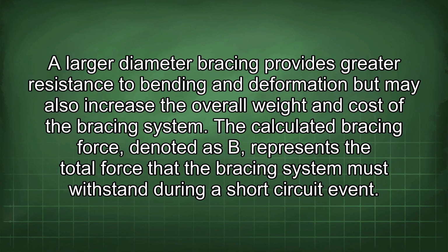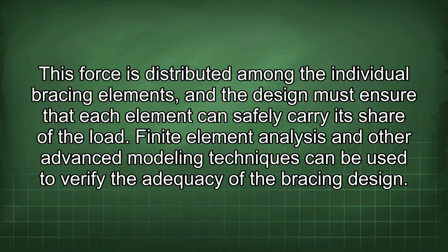The calculated bracing force, denoted as P, represents the total force that the bracing system must withstand during a short-circuit event. This force is distributed among the individual bracing elements, and the design must ensure that each element can safely carry its share of the load. Finite element analysis and other advanced modeling techniques can be used to verify the adequacy of the bracing design.